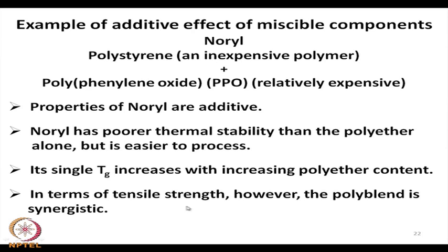Now, in terms of tensile strength, however, the polyblend is synergistic. In this case, although the Tg increases this way, the tensile strength gives quite an improved property at some particular composition, as I have explained earlier what we mean by synergistic effect.